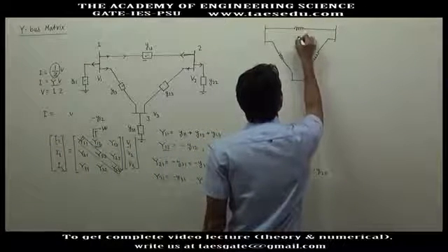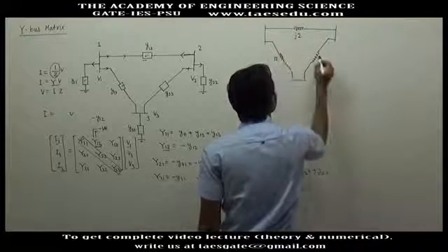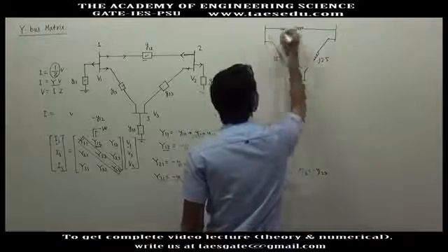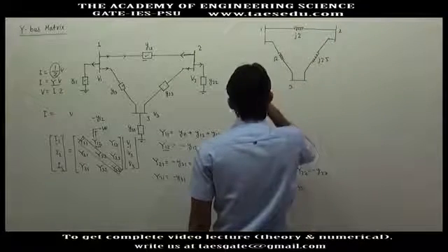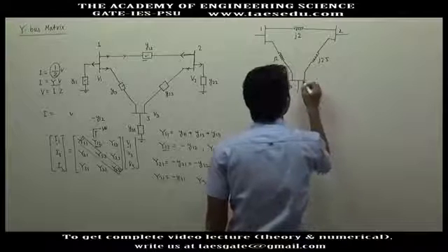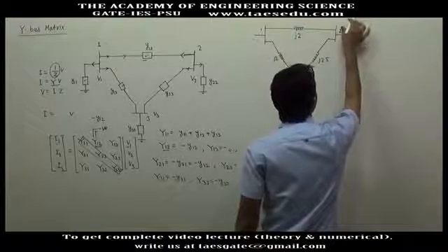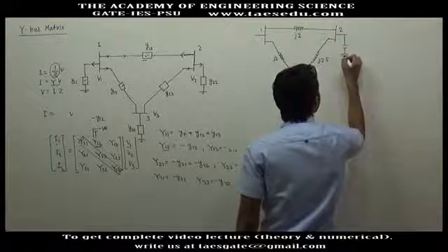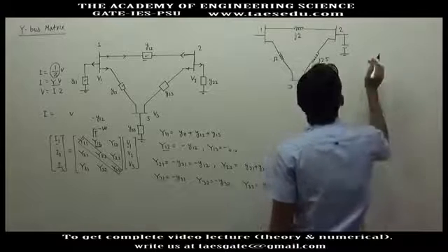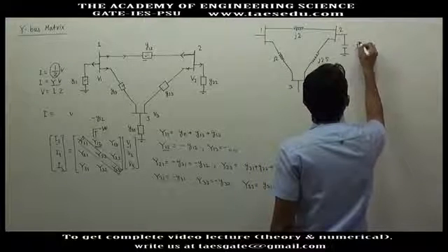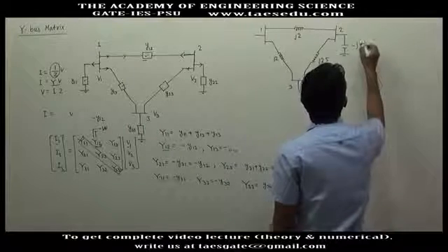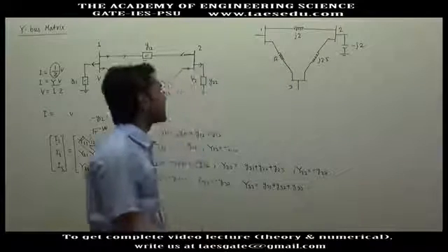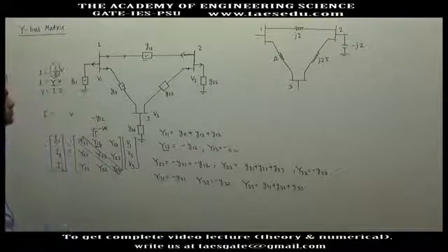Let's say this is J2 and J2.5. This is bus 1, 2 and 3. Okay, and let's say bus 2 has a shunt capacitor, and it is given as minus of J2, and you are required to find the admittance matrix for this bus network.